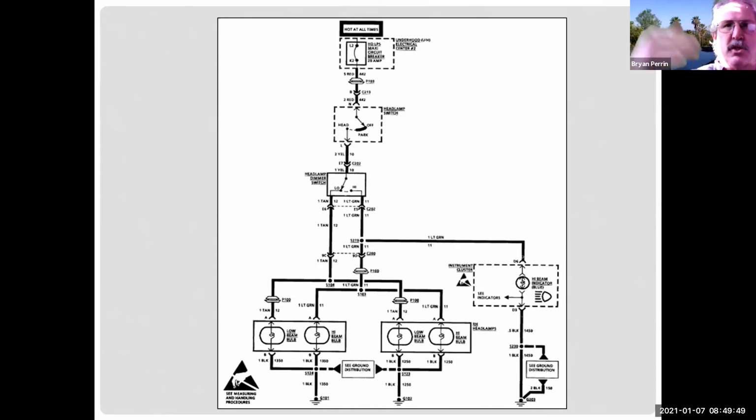Or I could go through this long step, and an example would be Honda for a throttle position sensor. The first thing you do is disconnect the wire at the sensor and at the computer and check all the wires. Step 23 has you actually test the sensor. Guess what part goes bad the most? The sensor. Wouldn't it make sense for me to go test the sensor first?